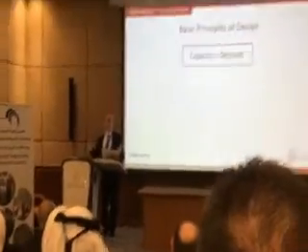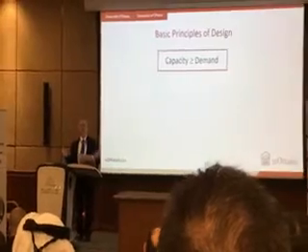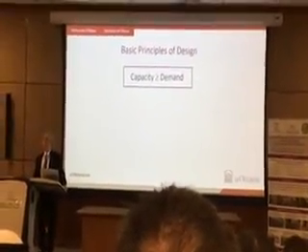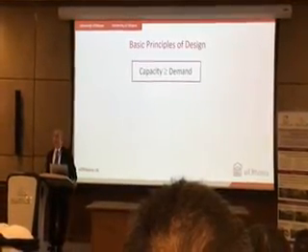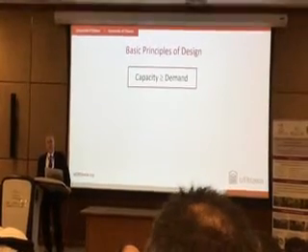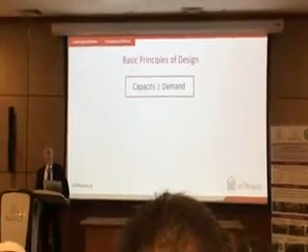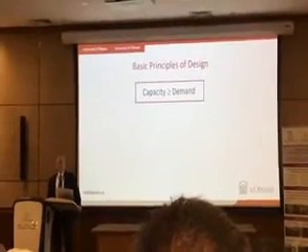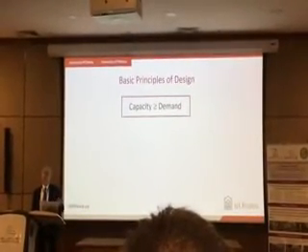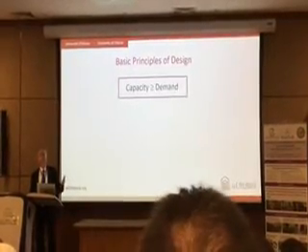So with this principal concept, blast being quantified with charge weight and standoff distance, now we will go into analysis and design, which is what structural engineers and civil engineers in general deal with. The same principle that we use in any design applies here. We have to have capacity of members higher than the demand. Demand is the applied force, what's demanded of the structure, and capacity can be force capacity or deformation capacity.